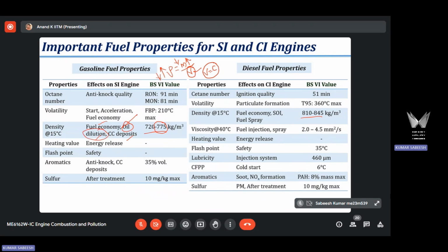You know, an engine has a separate lubrication system that provides lubricating oil to different components, including engine components like piston and liner and so on. So generally, especially between piston and liner, there is a boundary lubrication regime. You will have a thin film of lubricating oil present closer to the liner. Once the fuel stays in the liquid phase for long, it will blend with the lubricating oil. Fuel is a hydrocarbon. Lubricating oil is also a hydrocarbon.